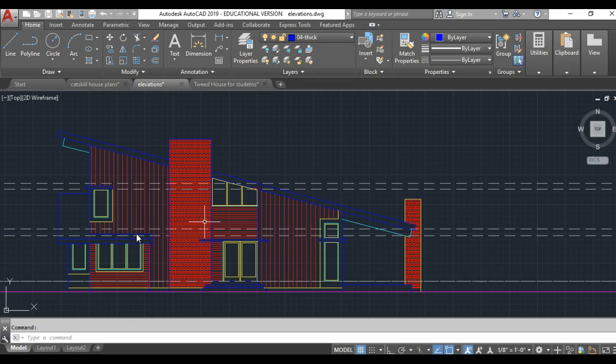Because, of course, the next major rule of determining line weights is things that are further away from you also step down in thickness. So we can see this fireplace chimney out here is actually quite deep in the plane. So that gets a yellow color in here, which is a very minor color in this diagram because it's further back, right? Now, yes, this plane of this house is technically a foot or two further back from this plane of the house, but it's minor.